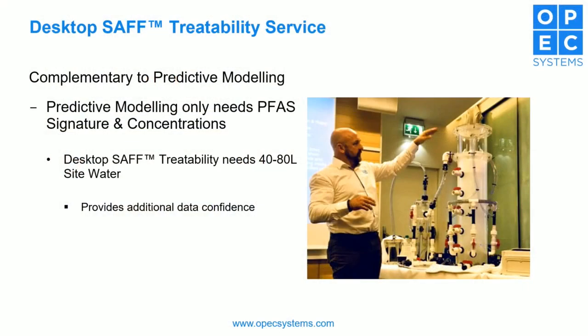So it's good, because Dave, this is what you've always been looking for, where we can do that desktop review of people's water and what it's contaminated with. So if people out there have laboratory test results of their feed water, you can email them to us. We can do a quick desktop review and give an indication of the % removal rates per PFAS compound. And then if you want a little bit more confidence, you can ship in 40 to 80 litres of water to our lab in Sweden, CDM Smith in Seattle, or our research partner here in Sydney, which is Macquarie Uni. We can run the benchtop.